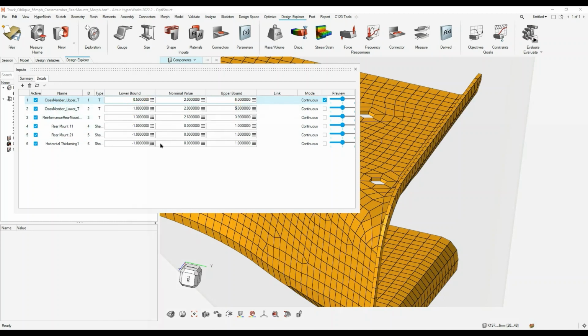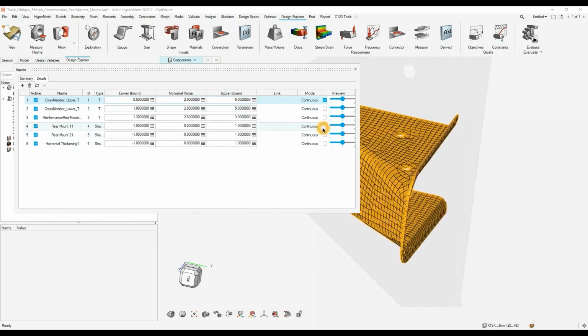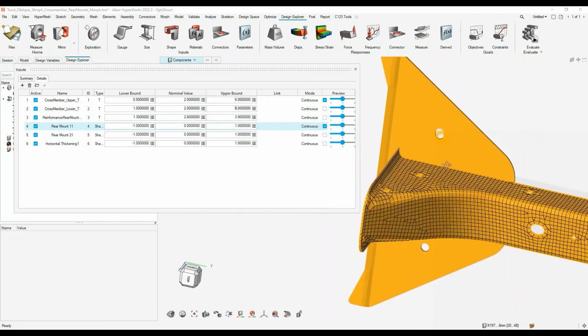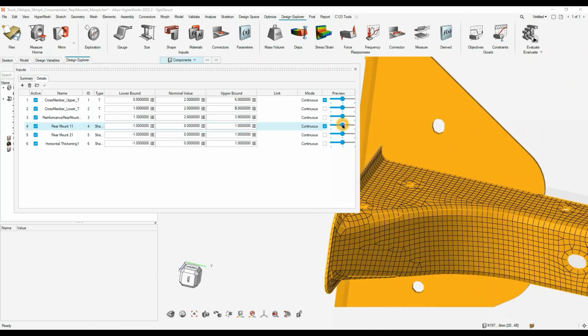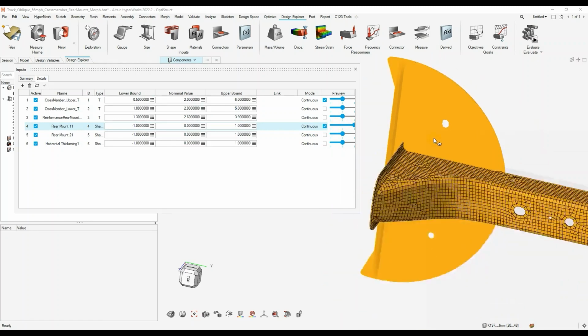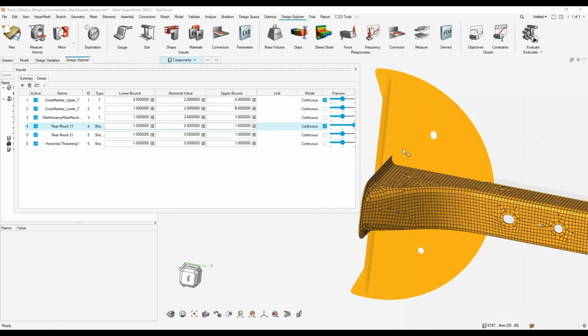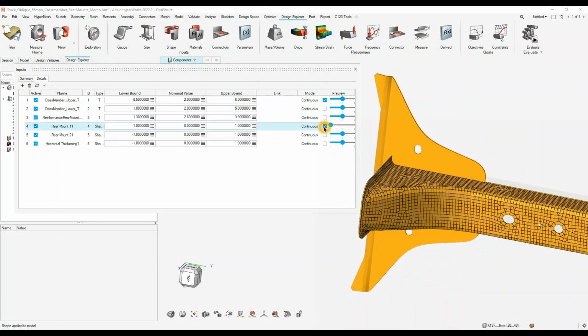You can feel free to adjust these as you see fit. And of course, when it comes to looking at the morph shapes that we have, you should think of the 1, -1 and 0 as a scale factor. So if I were to preview, let's say this one plate here, pushing it to the maximum will move it to the utmost extremity of that morph shape you implemented onto it. And if you go to -1, then it does the inverse of that design change you had.